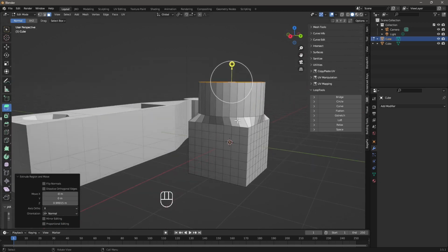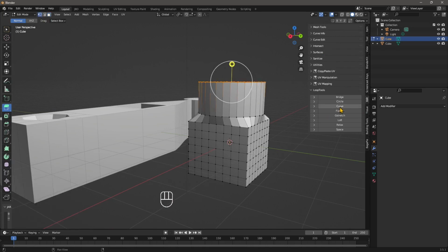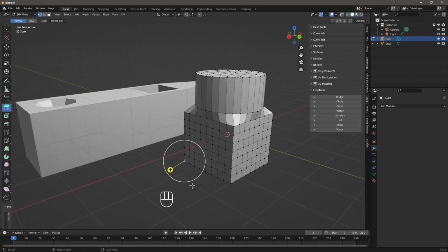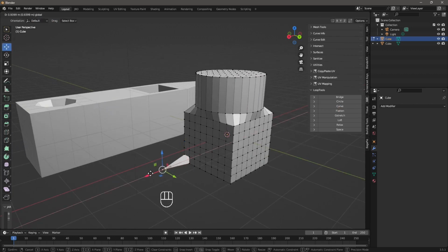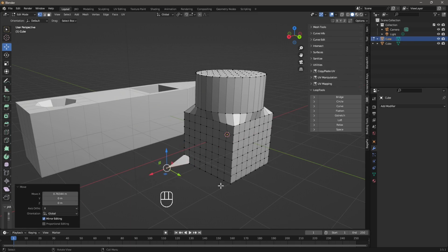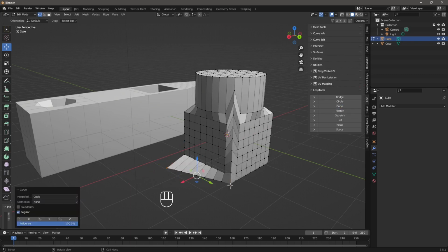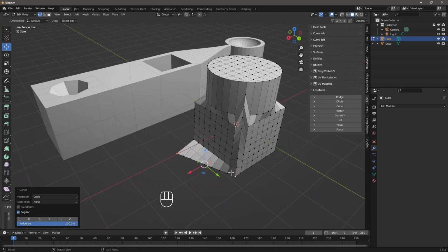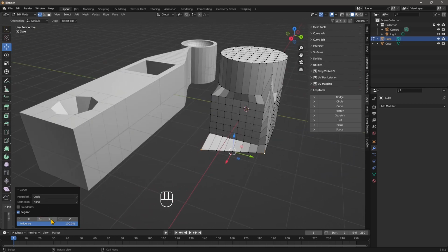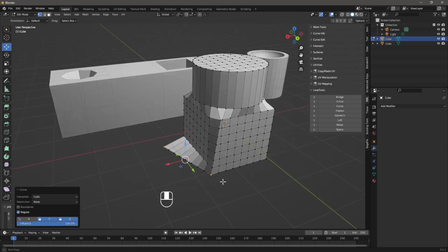And so now that we have some points here, I can work a little bit with the curve. So I can take, for example, this point, and I want to move it right here. And then I want to select these one by holding Shift, and let's do curve. So you can see it's kind of creating this, well, it's not a curve yet. It's kind of a straight oblique line. And also here, it's affecting also here. So we may want to, you know, restrain the effect sometime.